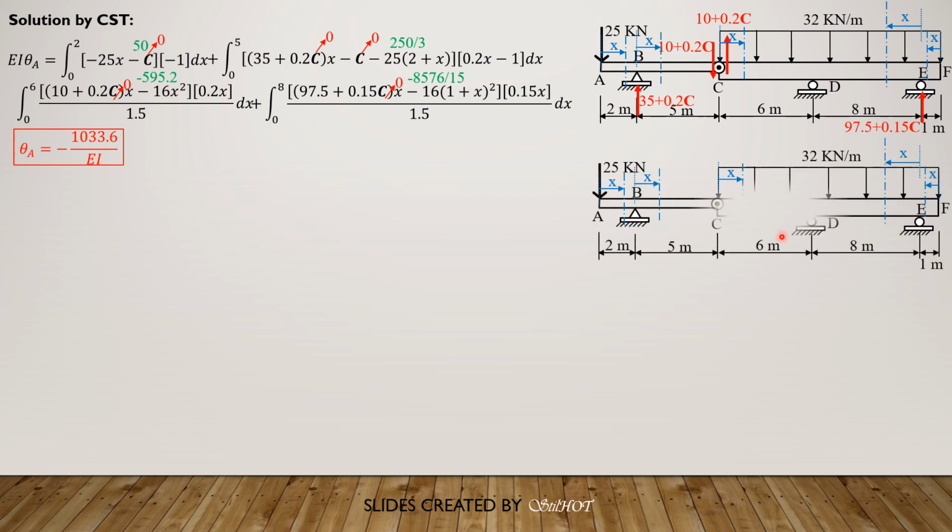Next, we apply a unit upward load at A. We remove these reactions. So an upward load at A, which is P. Then we compute the reaction here. Because the reaction here is 35 due to the actual loads, and it is upward, then it is 35 times 5 plus P times 7 equals 0.